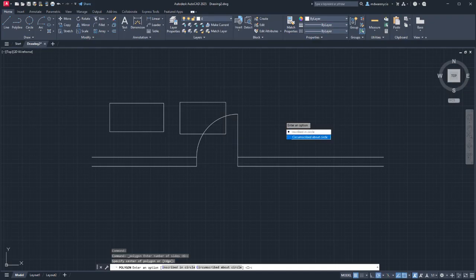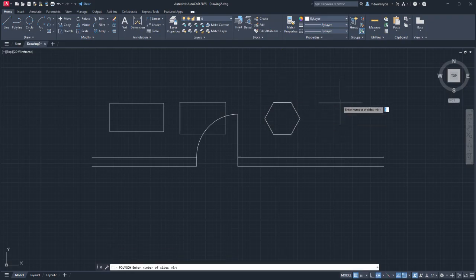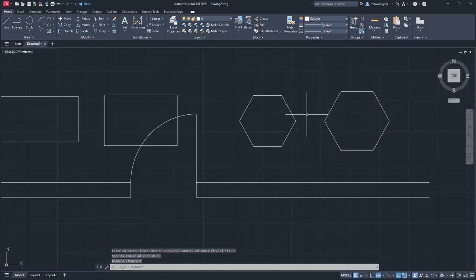where it starts. This tool actually gives you a couple options. You have inscribed in circle and circumscribed in circle, and I can kind of show you guys what those are just by doing two different things. So this is the inscribed, and if I move this up and do 1 foot, it's going to draw it there. If I do this and then switch it to circumscribed and do 1 foot, it's going to be that big.